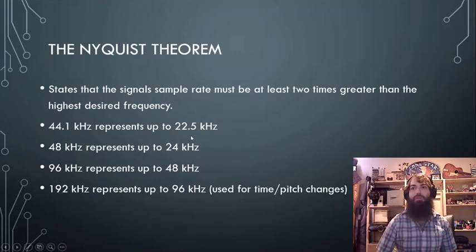So that means that humans, again, we can only hear 20 to 20,000 cycles per second. So CD quality, effectively, they made sure we had at least all that humans needed. So we can capture up to 22.05 thousand cycles per second. A lot of times, though, nowadays, a super audio CD uses 48,000 samples per second, because that can represent up to 24,000 cycles per second.